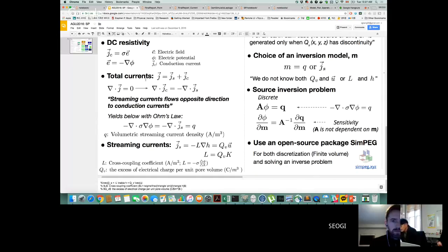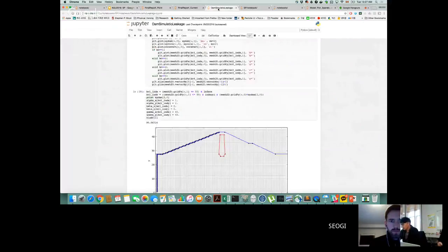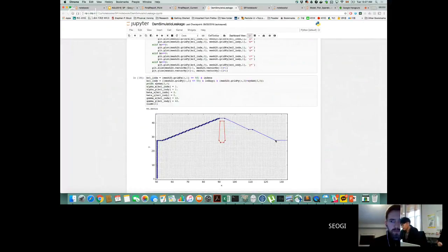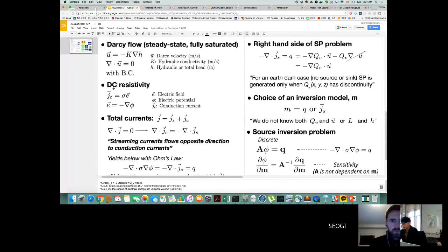So do you render air cells inactive, or is that a triangular mesh with all the cells that you have in the entire problem? Just curious how you organize it. So I'm actually only solving inside of this blue line. I'm not solving above. I generate the mesh, and then you cut it off. But you need to be a little bit careful about the boundary condition when you're doing that, because you need to find all the corresponding faces and then define your boundary condition. So that's with BC.